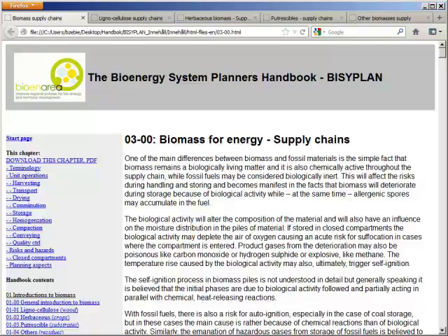For the storage of bio-oils that have not been chemically stabilized afterwards, after the production, but the simple bio-oils, such as pyrolysis oil or cold-pressed oils, it is highly recommended that the tanks are continuously agitated and they are also heated, so as to keep the oil flowing and homogeneous.